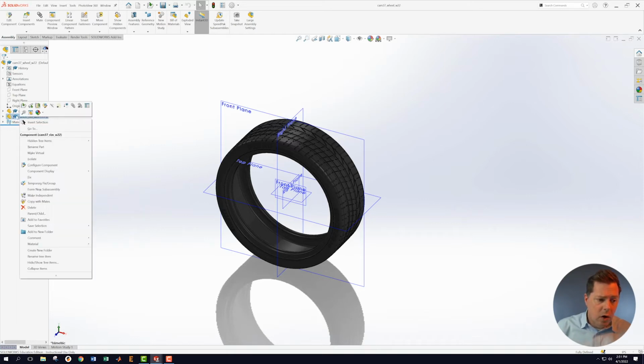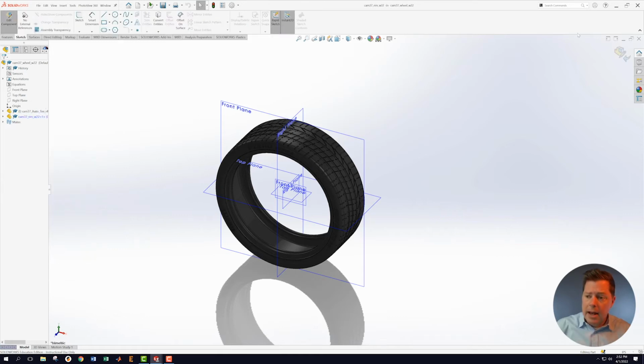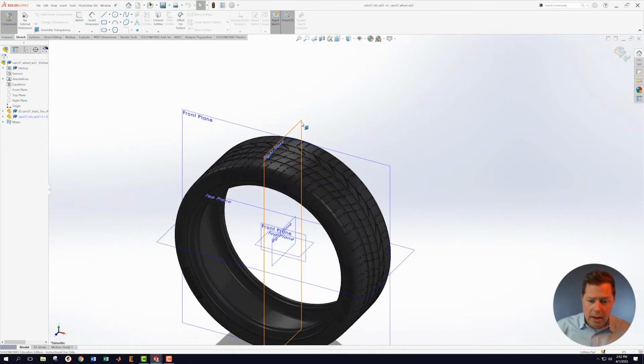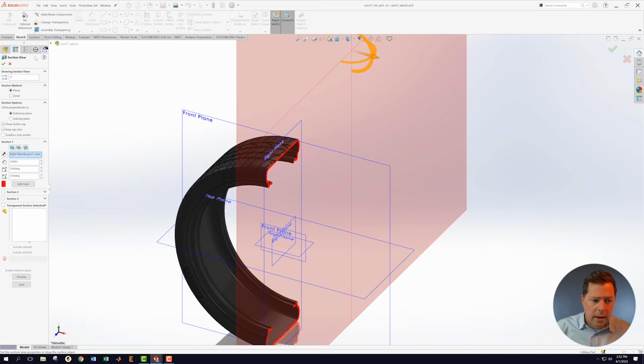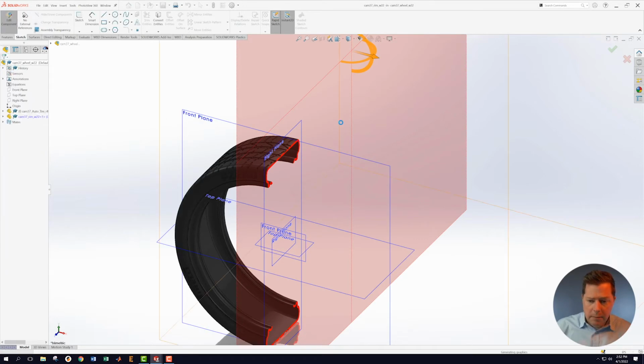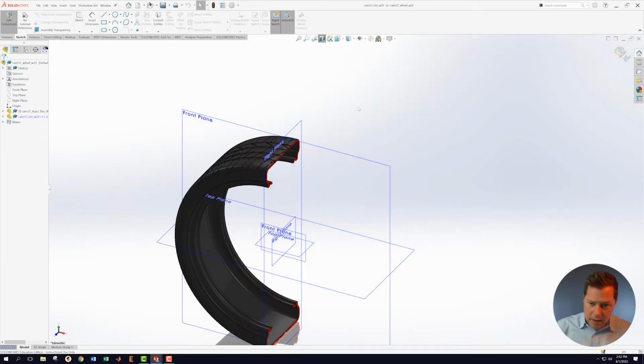What I'm going to do now is go in and edit the part. I could open the part and edit it in its own window, but I'm going to do master modeling, so I want to just edit the part in place. And I can see by what's in the top right corner of my screen right here that I am editing in place. And what I can do now is go in and get the surfaces that I want to take over into the rim model.